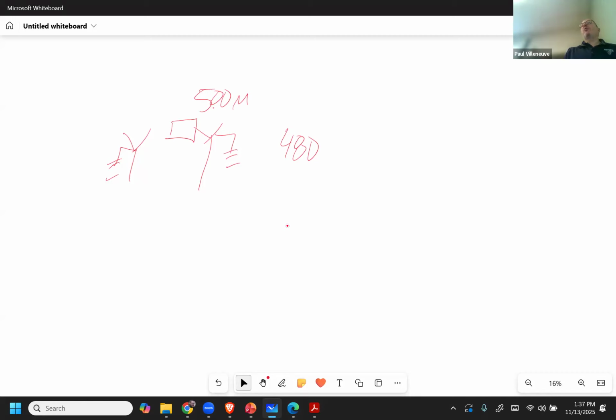So distribution circuits, you don't worry too much about ground because most of the time your individual loads are going to be like 30 amps or less. So you don't even care about the distribution ones. At the substation, the substation transformer, so this would be like a 5 MVA, those would be configured like this. This would be the 35, or if it's Versant territory, this would be 46 kV, and this would be 12.47 kV, and they would have a delta Y there because they're trying to isolate sub-transmission and distribution in terms of the protections that they